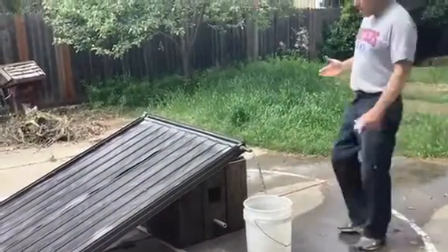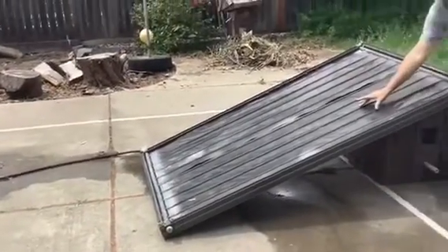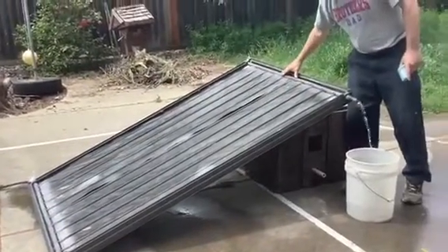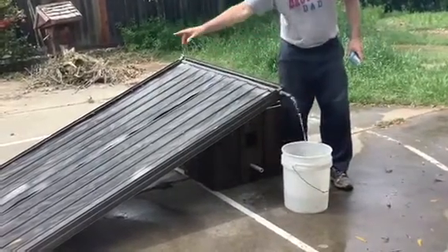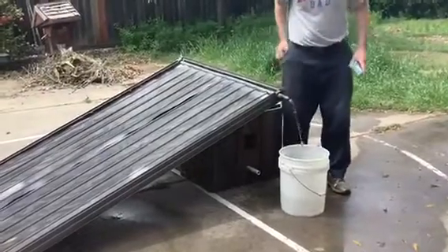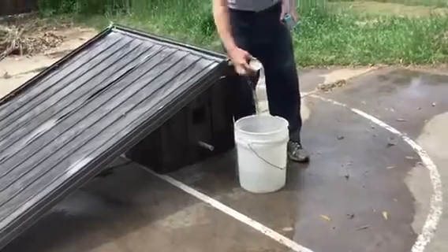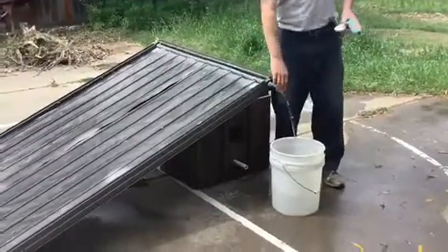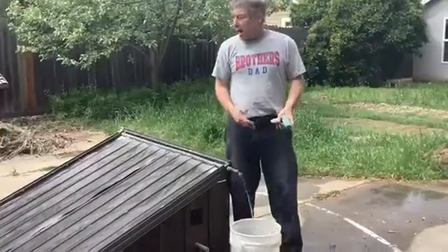Okay, so we got it up and running. If you look down at that end, the water's coming into the main pipe. It's going up these riser pipes, collecting in this top pipe right over here and coming out. The inlet water is about 60 degrees, and this is coming out about 71, 72. If I use this thermometer to verify, I'm getting about a 10, 11, 12 degree rise as we're going through, and we're collecting that hot water in the bucket.